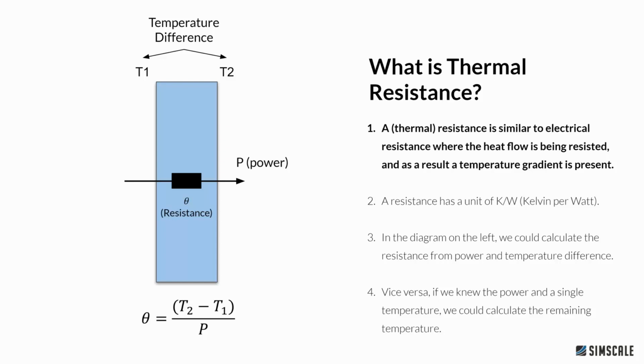In some cases, very kindly, the manufacturers give us the resistance values from physical testing. They would put their component onto a test bench, and measure the temperature on each of the sides, the top, the bottom, and at the junction, and calculate these resistances for you.